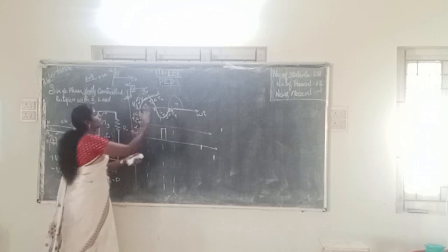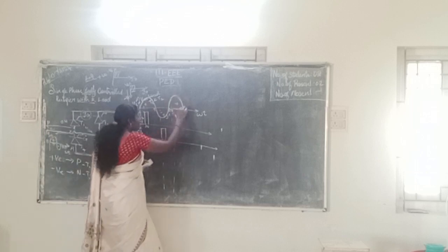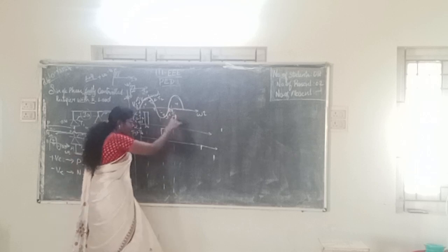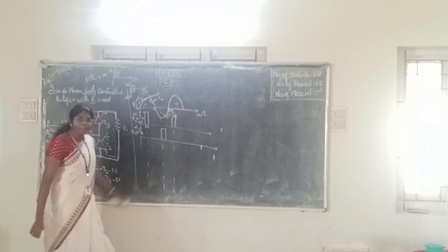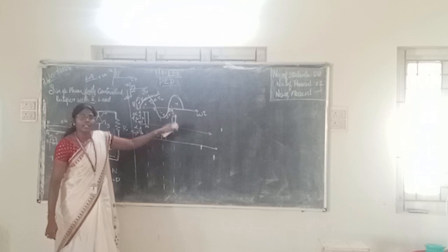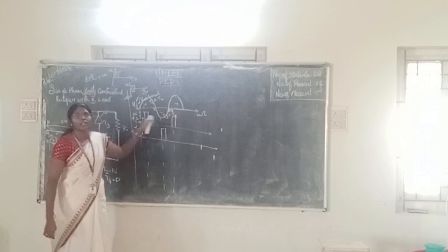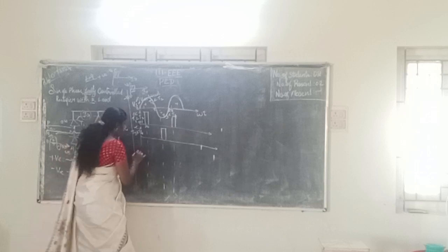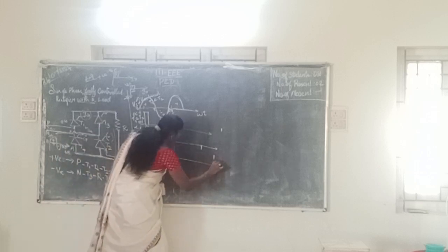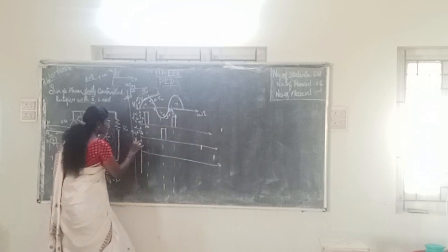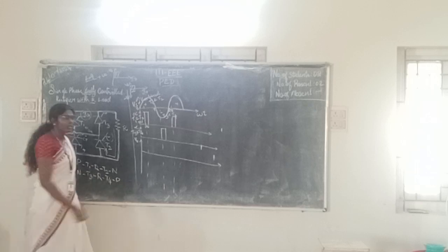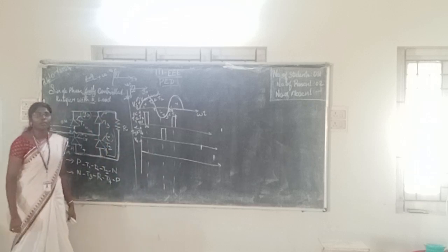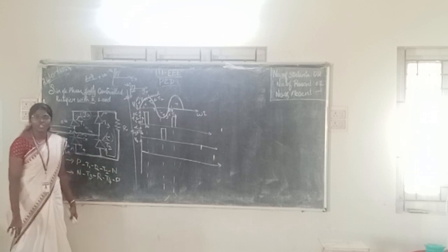Likewise, during the next half cycle, that is the positive half cycle, this is where the firing alpha will be in the next cycles. The next positive cycle, T1 and T2, will continue. So then how will our output voltage waveform be? Our output voltage will be 0 initially.